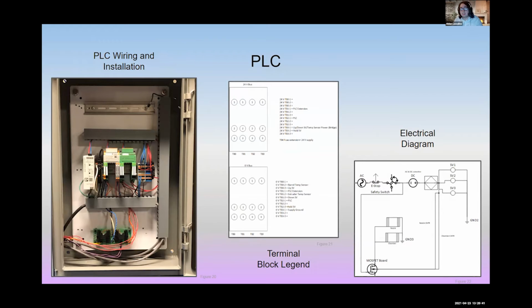Overall, our PLC is complete. We have it functioning and wired up completely as intended, and we are able to regulate and control the heat of both the nozzle and the barrel under 250 degrees Celsius. As well, the PLC can control our pneumatic solenoids, which allows for actuation of the piston through code.